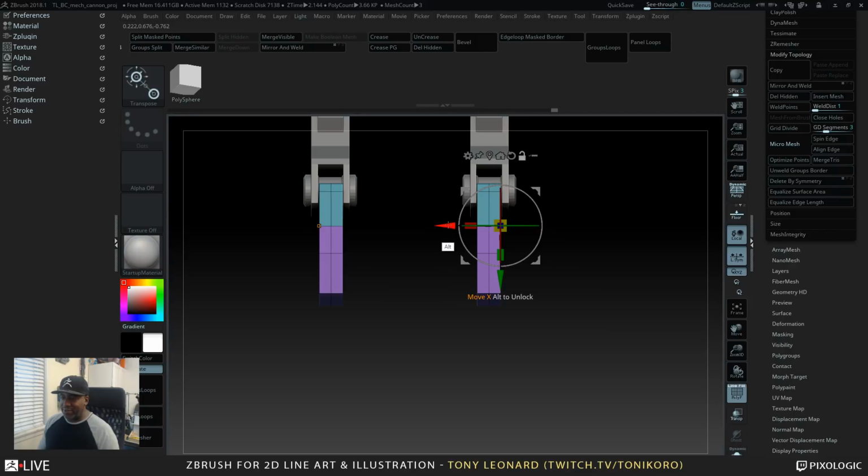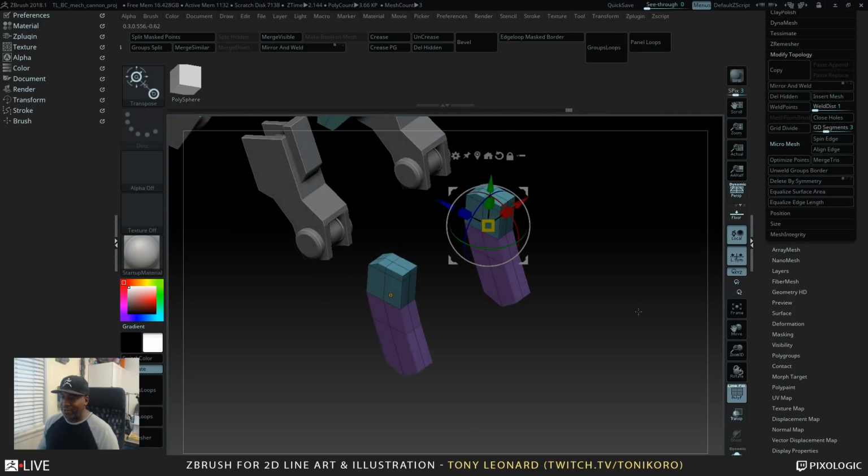So let's say, for example, if I position this with Alt and then Shift and sliding in one direction, you can sort of center it to the piece. You can hold Alt again and rotate this, so that hitting Shift, we're snapping to the 5 degree and just doing a total 180 that's straight up.